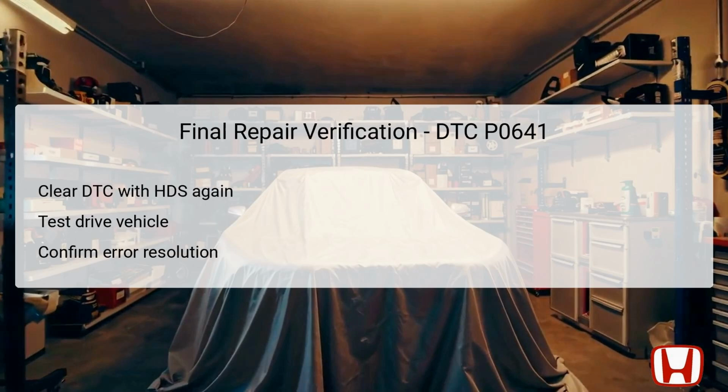After completing the necessary repairs based on the prior steps, it's crucial to verify that the problem is truly resolved. Begin this process by clearing the DTC with the Honda Diagnostic System, HDS, once again, ensuring that any residual codes are removed from the system. After clearing, conduct a thorough test drive to simulate normal vehicle conditions and check if the DTC reappears during operation.